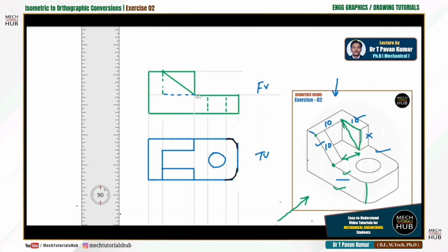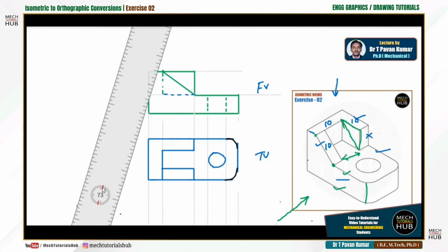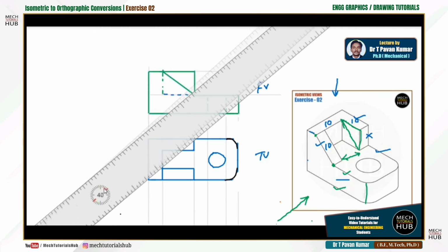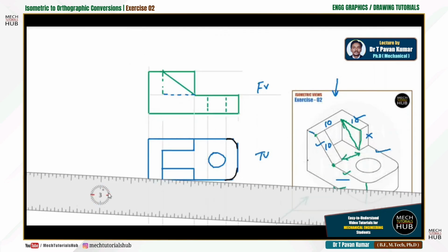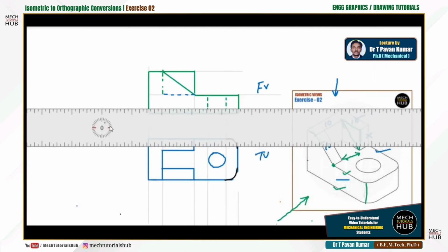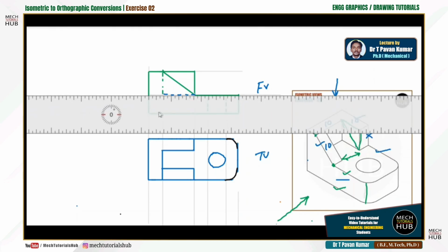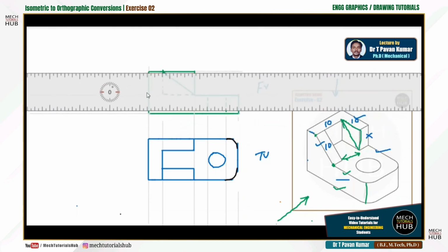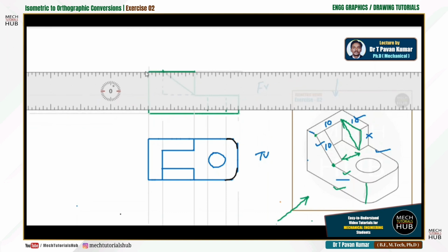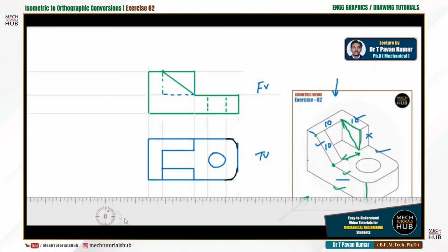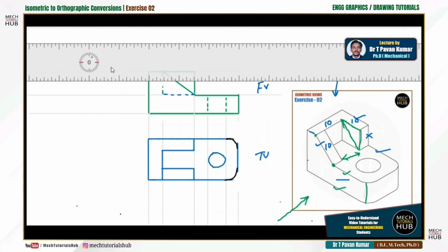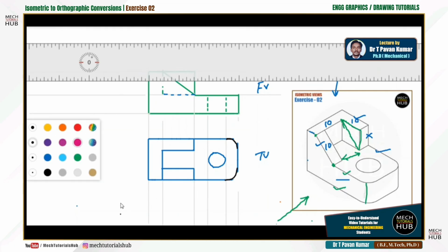Okay, other than this, to draw the side view, as I said in the beginning, you need to take the extension of every edge. So for that again I'll consider 2H pencil and draw horizontal at every edge. This is 1, this is number 2, any infinite distance, no need to erase at a later stage, keep it as it is, number 3.